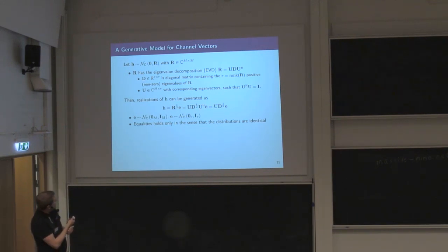And in that case, when you have this Hermitian transpose of a matrix containing the eigenvectors, multiplying that with a complex Gaussian distributed variable with covariance matrix I, this thing here will just take away M minus R of the dimensions, where there is nothing in U that spans it, and you will reduce the dimension.